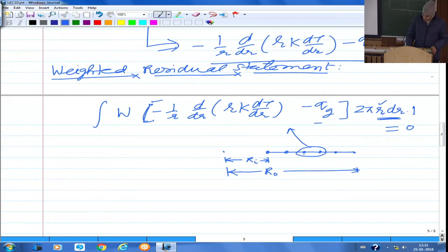One more thing I am going to do: if you look at this differential equation, it is a differential equation with variable coefficient, since r is coming in. Of course, I have an option to take the origin of the local coordinate at the first node of the element, but then this r is a global r, the radius of the cylinder at that point, so that has to be taken care of. The other option is that we write our approximate solution in terms of the radial coordinate, so my origin for radius is here, measured from the axis of the cylinder. Let us say the radius here is Ri, and the radius of this point is Rj. Starting node radius is Ri and end node radius is Rj.